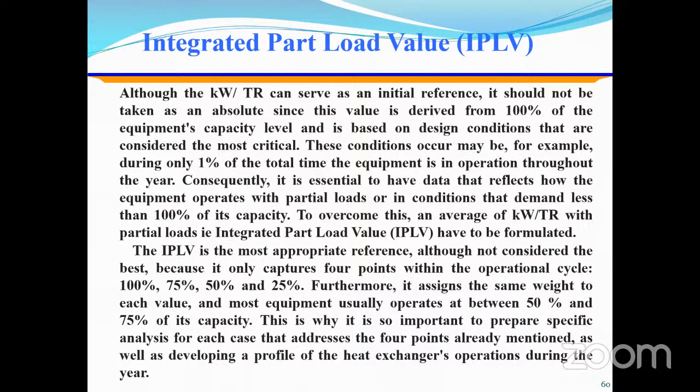Based on that, there is a BMS, building management system. It sends the online monitoring of operation of the HVAC system. So based on the loading condition in the building, it should automatically control the chill water to the AHU unit, that is evaporator.